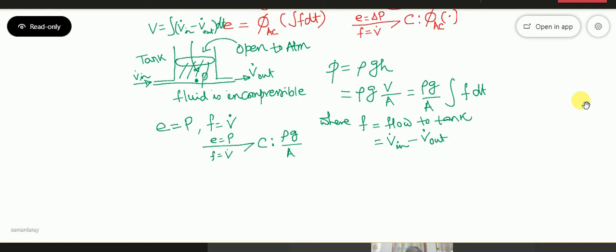What we considered was the pressure due to the air, because that was the dominating factor there. Here, the atmospheric pressure is negligible, it's the same everywhere. What is dominating is the height of the head of the water. So we consider that, and this kind of a linear model comes, whereas the accumulator gave a nonlinear model.